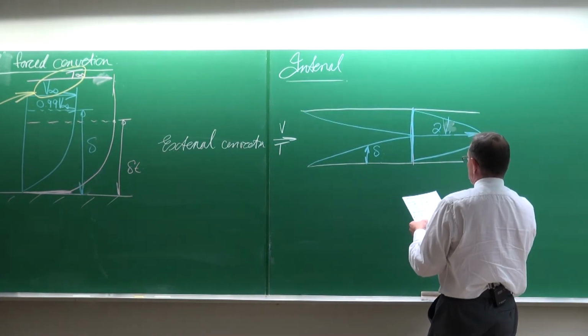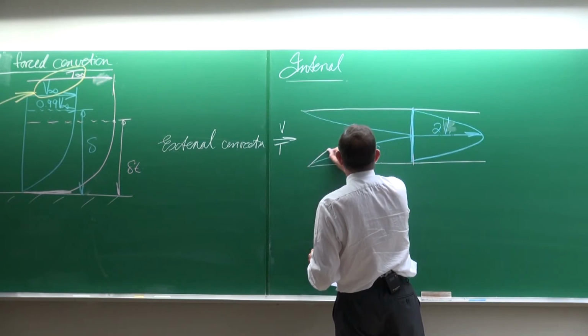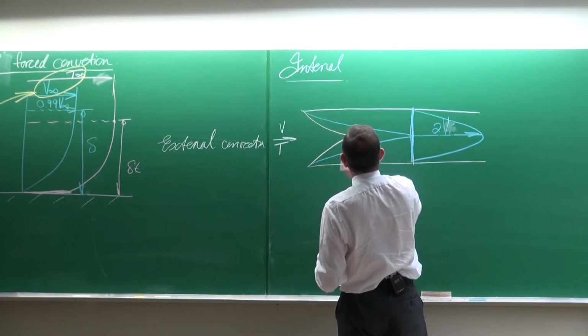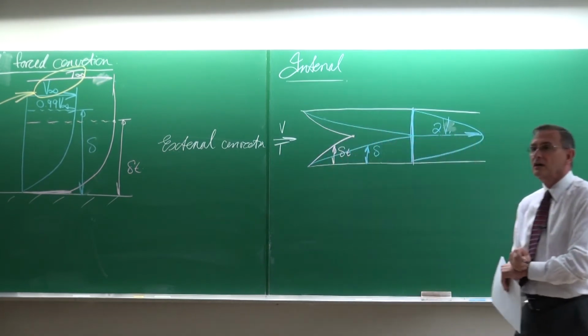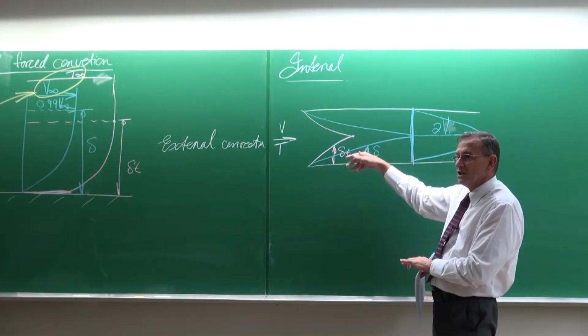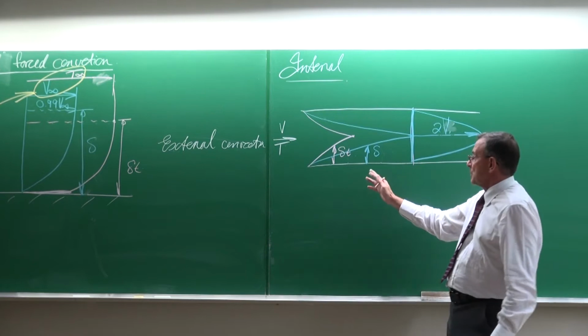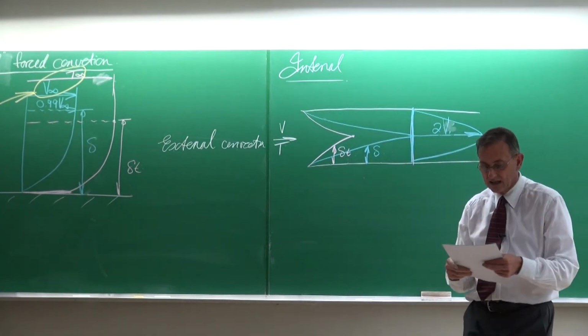And the other thing that is noticeable, if we now look at the thermal boundary layer, I'm going to draw it there just to show it. In this case, it develops quicker than that of the velocity boundary layer, which determines which one is the quickest, the Prandtl number. If the Prandtl number is equal to 1, then these boundary layer thicknesses will be exactly the same.